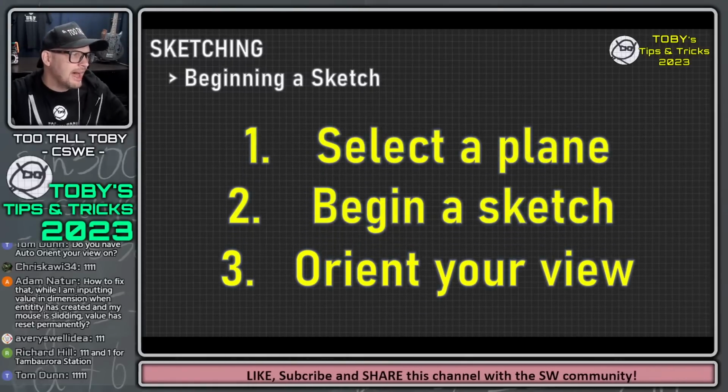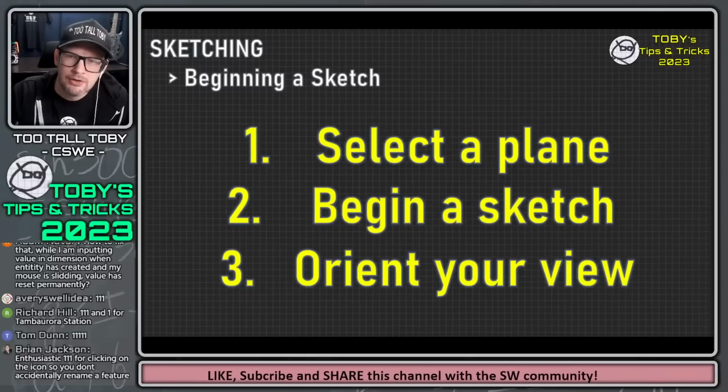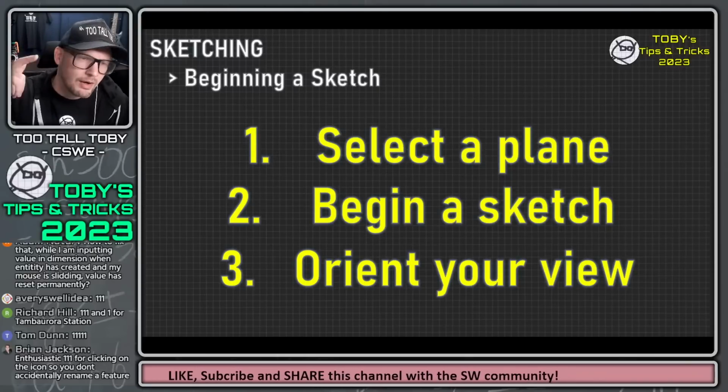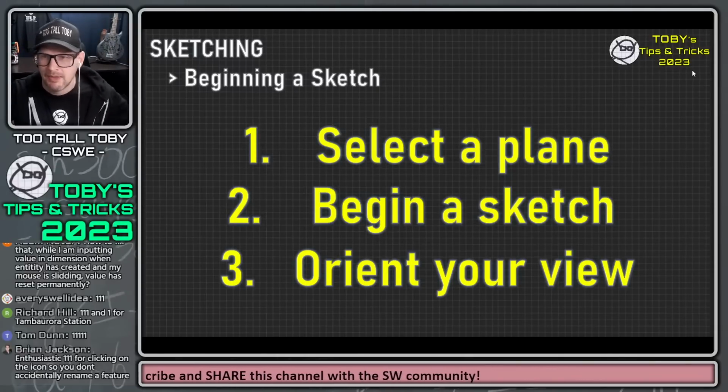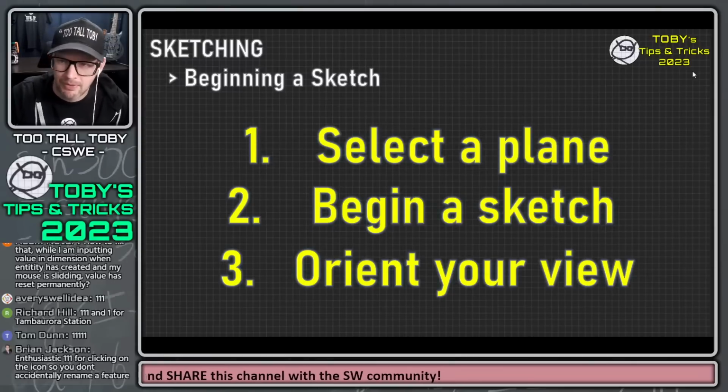Cool, so select plane, begin a sketch, orient your view. That is the way you want to create a new sketch, and you want to remember, don't use the icon up in the toolbar. That will be problematic.